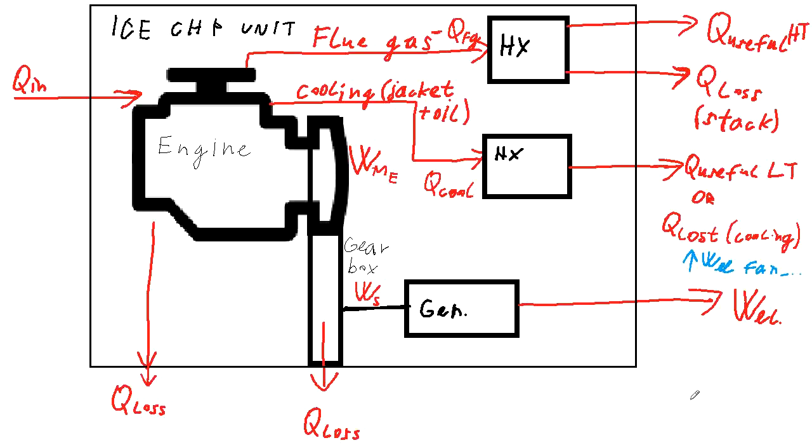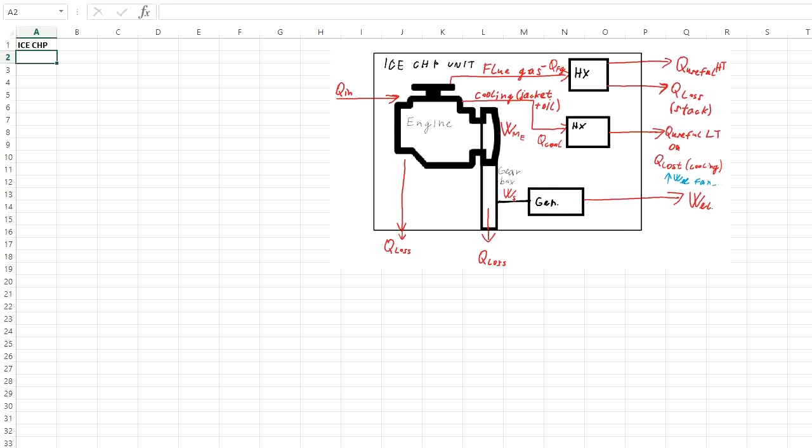So now we have put together the schematic balance model of the system, and now we will add the calculations of each stream and their parameters. So let's start with summarizing the input parameters, which was the electrical power output, 104 kilowatts. Then we had the volumetric fuel consumption, which was 28.3 normal cubic meters per hour.